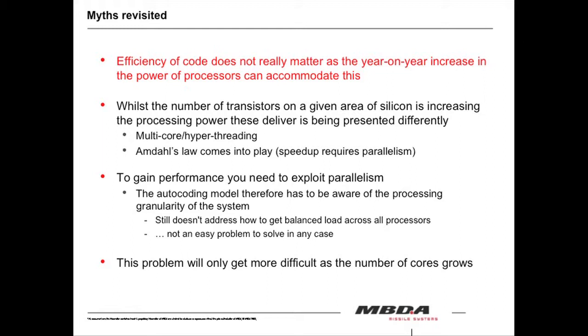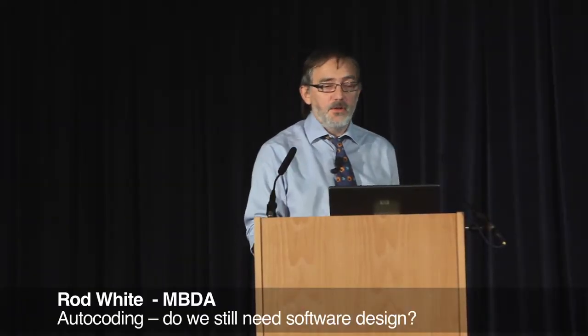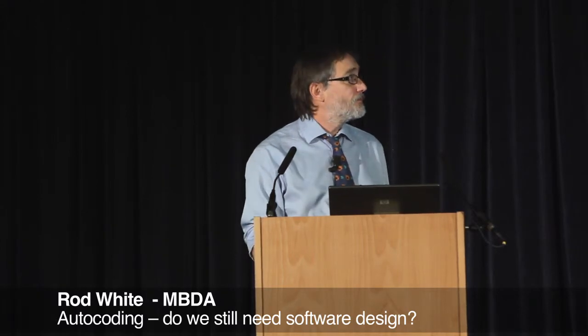If you think about the way in which processors have speeded up over the past 20 years, does a PC running Microsoft Word run 100 times faster than it did 20 years ago? No, it certainly doesn't. In my own domain, when I first started working with real-time embedded systems, the interrupt rate was probably a millisecond between interrupts. Am I really saying that with processors now 1,000 times faster than when I started, I would even contemplate handling rates of a microsecond per interrupt? Absolutely not. It's just not sensible. So that doesn't follow.